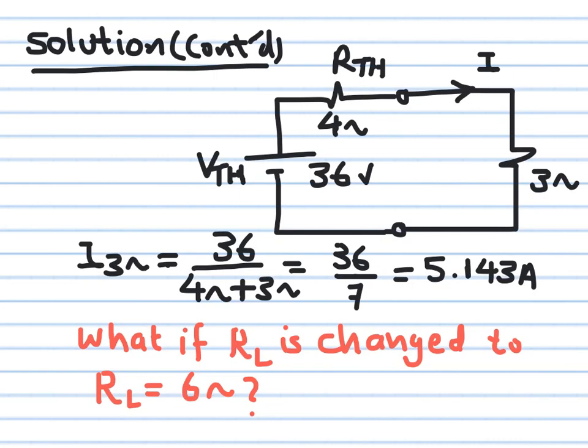So this is the great thing about the Thevenin equivalent. It is independent of the load that you connect. As long as you found the Thevenin voltage looking into the circuit from between any two terminals, then you can later connect any load to these two terminals and calculate your currents and voltages and so on.